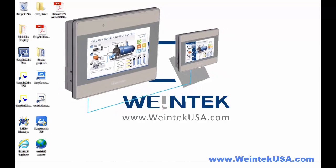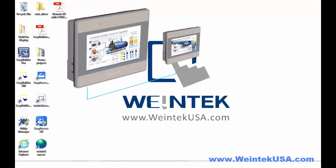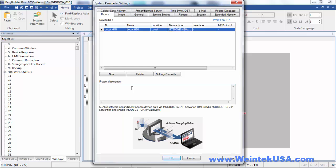In this scenario, we will be setting up communications between two HMIs. Now please note, if you are not using a switch between the two HMIs, it's recommended that you use a crossover cable. In this example, we will be setting up communication between two HMIs, in this case a cMT-3090 and an MT-8050IE. I'm going to start out with the 8050IE.